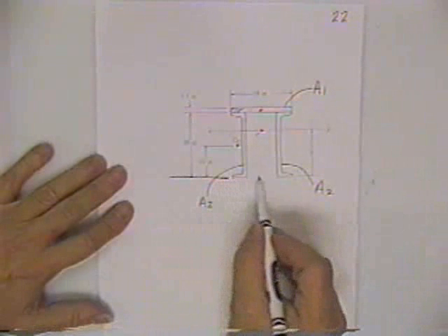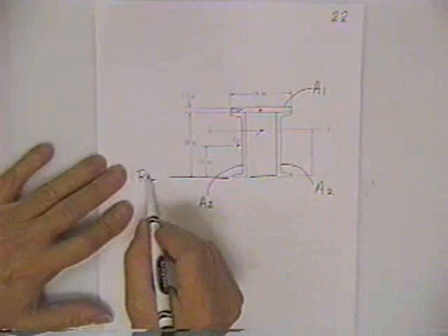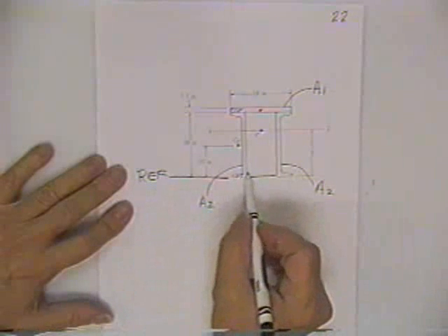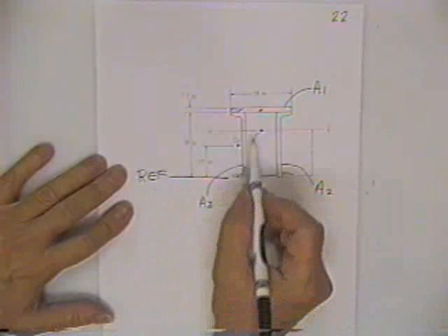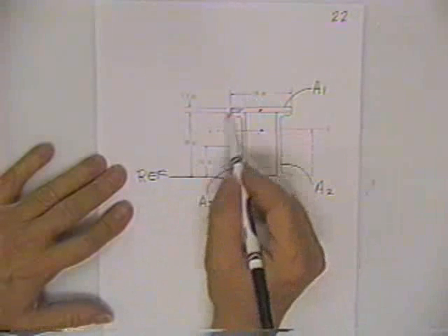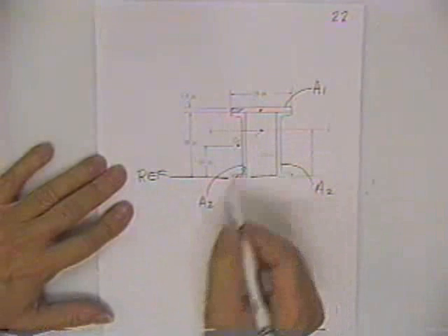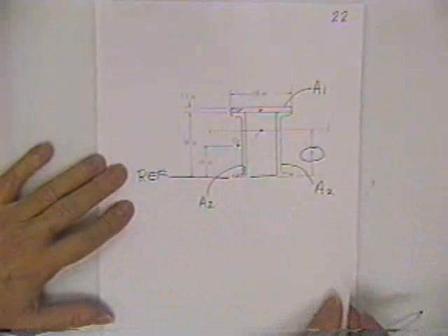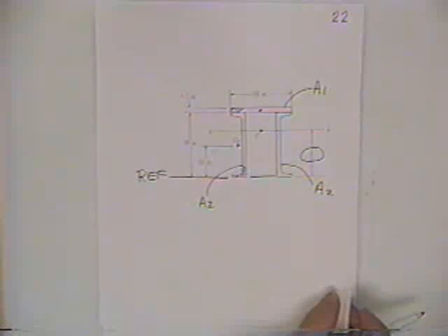Draw a reference axis at the base and apply the same equation. You would have to be told the area of these shapes. This area, of course, is 18 by 1.5 inches. Then you get how far up the centroid is by the same equation.